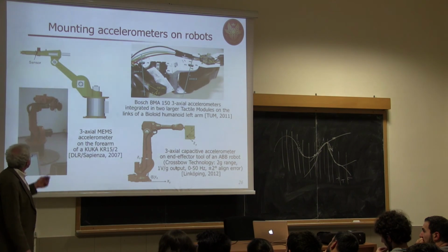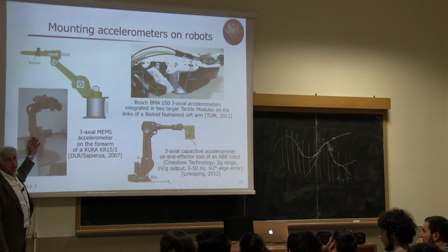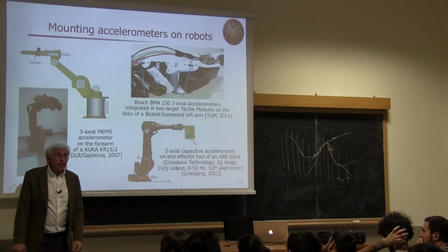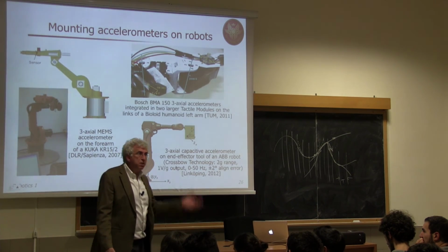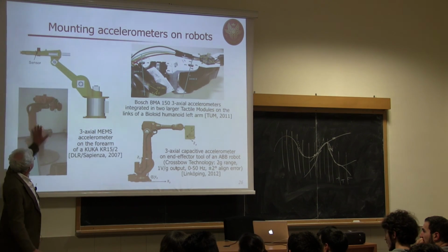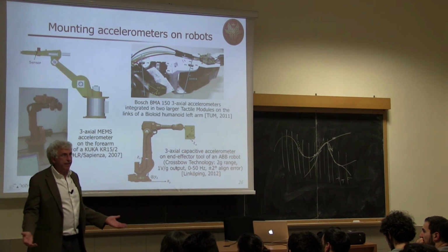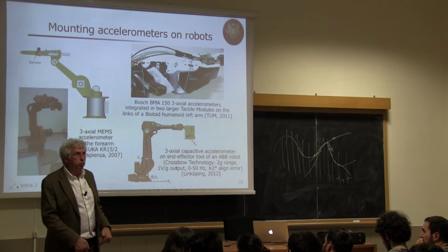And this is because this robot used epicycloidal transmissions, which are in fact elastic, so that the measurement on the link side becomes part of the full state of the system. If the system was fully rigid, remember, only position and velocity of the joints make up the full state, and the acceleration becomes a function of the input torque.